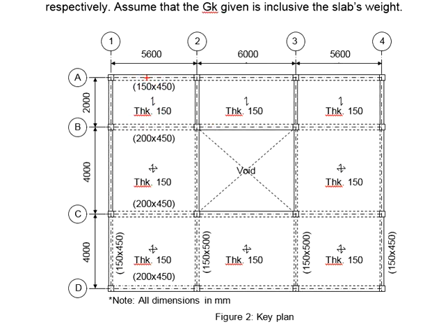The slab is only subjected to the bending in the shorter span, whereas in the longer span, the bending moment will be negligible. In this case, most probably you do not need to design for the resistance of the moment in the longer span, as you cannot find any bending moment in the longer span when it comes to one-way slab.